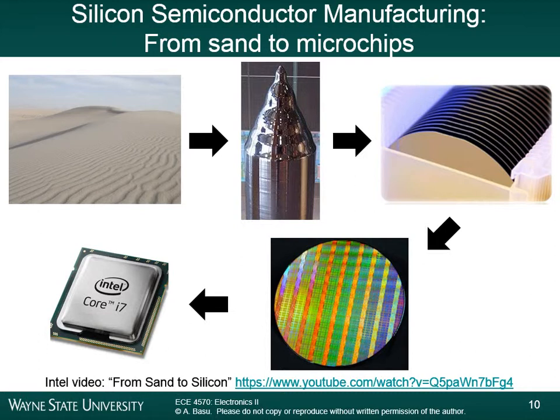So it's a series of steps called photolithography, where you optically define where you want your transistors to be. A transistor, if you remember the picture that we saw earlier, consists of a p-type region and an n-type region, and there's a gate region, for those of you who remember from Electronics 1. So when someone does what's called electronic circuit layout, you're literally indicating which regions are going to be P, which regions are going to be N, where the gate is going to be, and where the source and the drains are going to be. And you do that for each transistor on your chip.